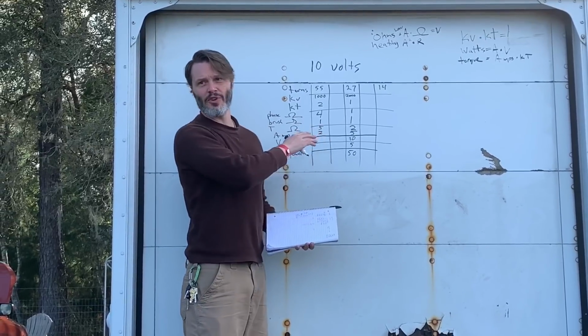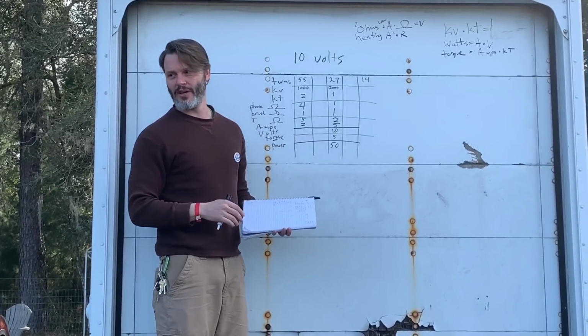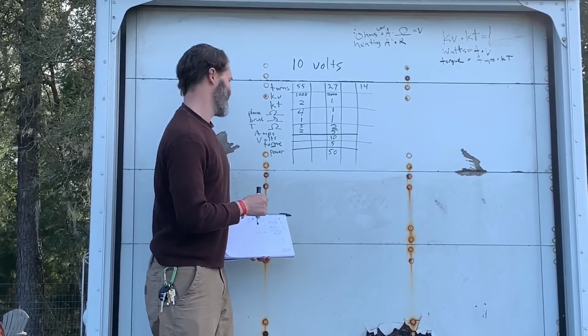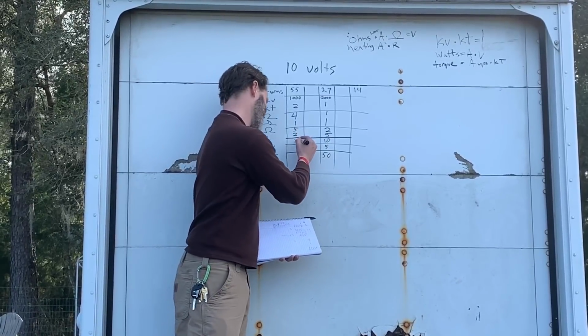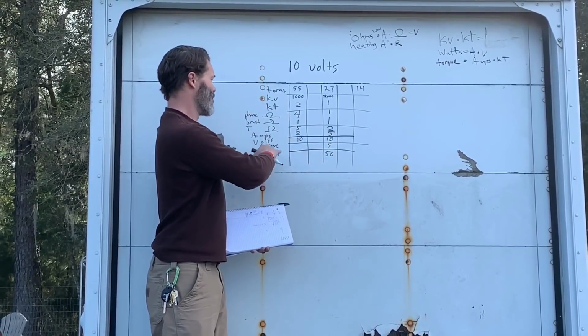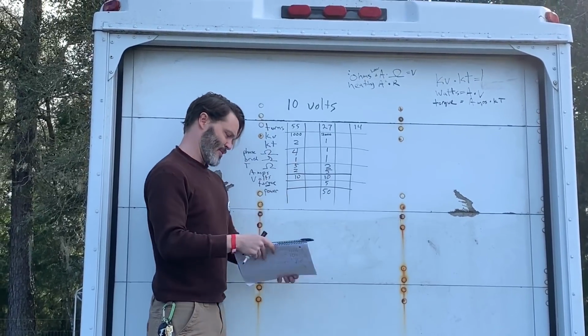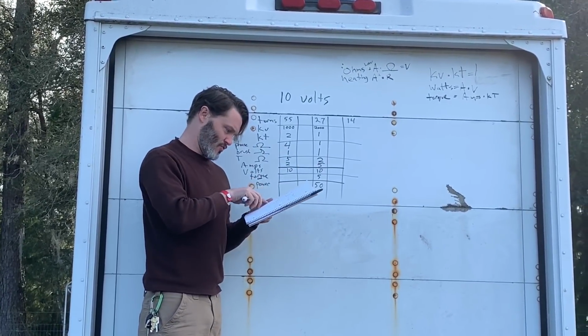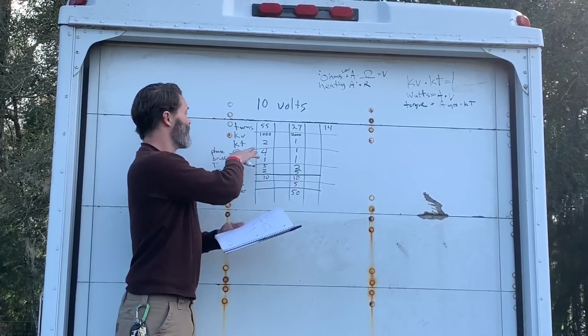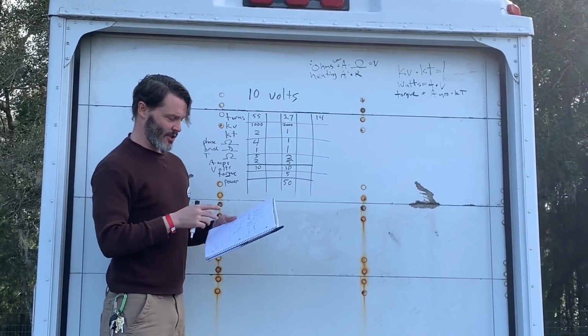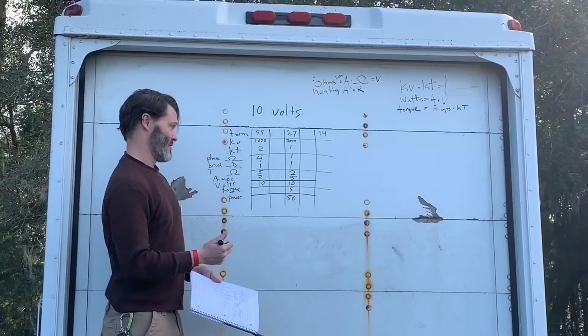Again, our torque units are not going to show us what the real torque is going to be, so we're not applying units to it, but it is scalable. All right, so our volts were still at 10. Our torque now, we are pulling 2 amps. Let me make sure I'm doing this right. 2 amps. Our torque constant is 2, so 2 times 2, what are we at now? 4.